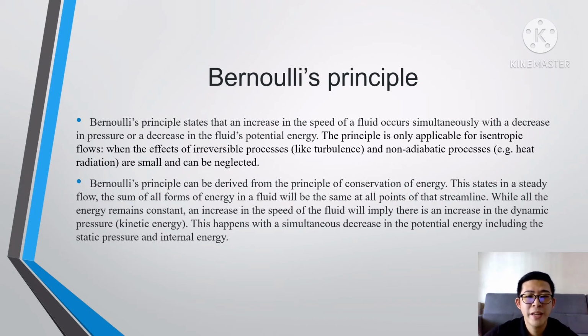Bernoulli's principle states that an increase in the speed of a fluid occurs simultaneously with a decrease in pressure or a decrease in the fluid's potential energy. The principle is only applicable for isentropic flows, when the effect of irreversible processes like turbulence and non-adiabatic processes like heat radiation are small and can be neglected.